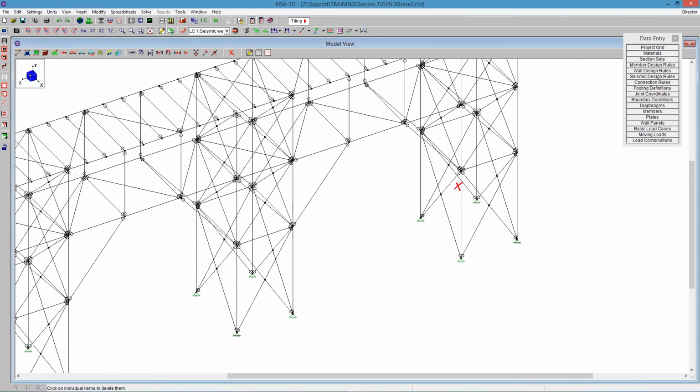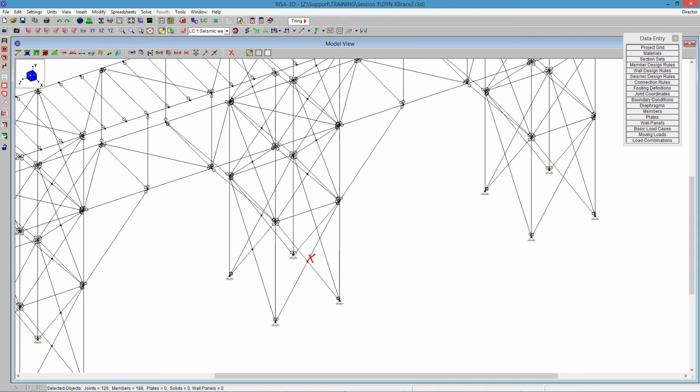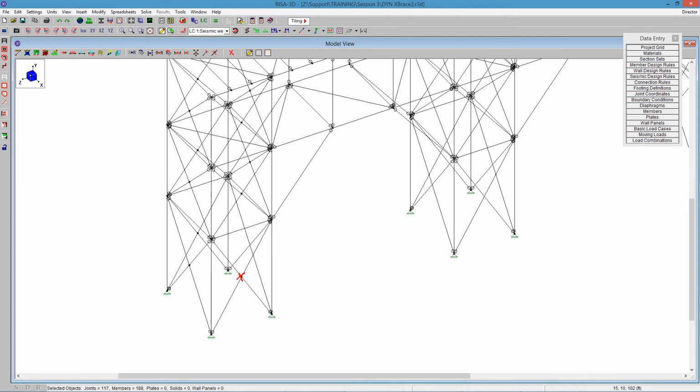If you needed to brace these at those locations, you could just do that manually for the design results, but you don't need to actually put a node so that those contribute to each other. Typically, X braces don't contribute at their X's there. You don't usually connect them. So you can delete a lot of these here. I'm just going to delete all my nodes that are going to be causing this crossing. What that does is eliminate all those nodes, as I mentioned. Hopefully, we see that cleans this model up, and we get to see a little bit better global contribution of that mode shape versus the local.